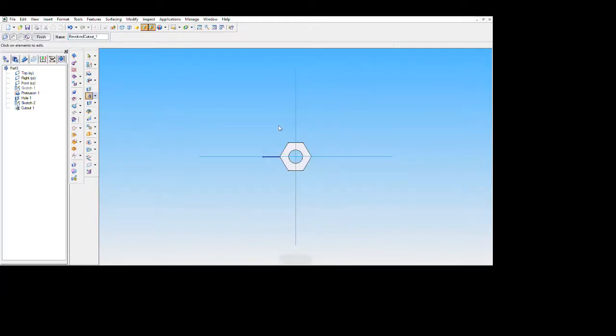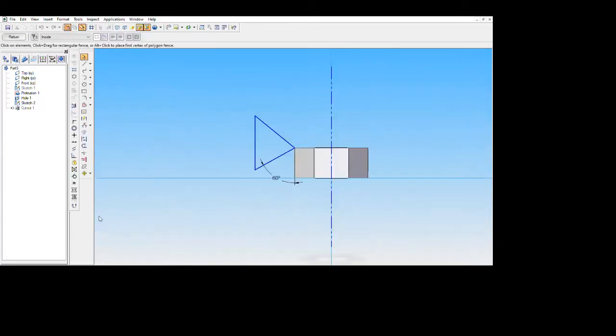I'm sorry, but the cutout was too short, need not to worry. Go to the select tool, select on sketch number 2, right click on this, go with edit profile. Now move this triangle from here. Select the move option, select this entire triangle, move it from this point to somewhere here.